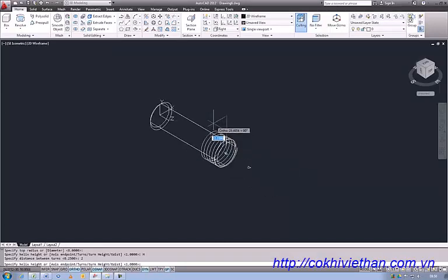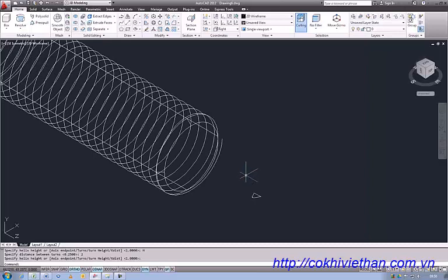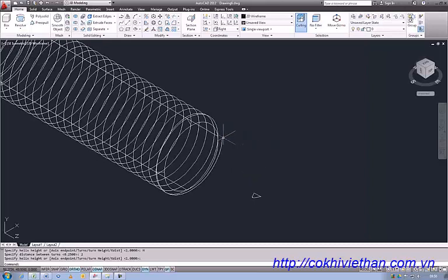So what we need to do is drag it to the top left hand corner, and I'd advise dragging the helix a little bit past the end of the bolt, because later on it makes selection slightly easier. So drag it past and then just left click, and there we have, I'll zoom in a little bit, our helix, and it should start on the 3 o'clock quadrant here if everything has gone okay.